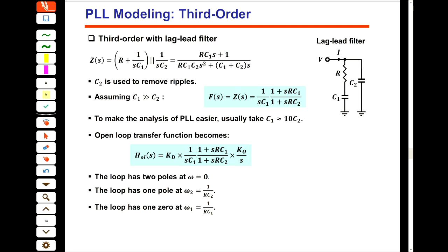This is the total current. Assume that this is IB. In circuit 1, we have one voltage here that I don't know, and one voltage here that I don't know. So this is VO, this is V1, and this is V in. For example, this is one voltage, this is one voltage, and this is one current. I have 3 variables, so I need 3 equations to solve them. So we'll apply KVL or KCL, but they should be independent.